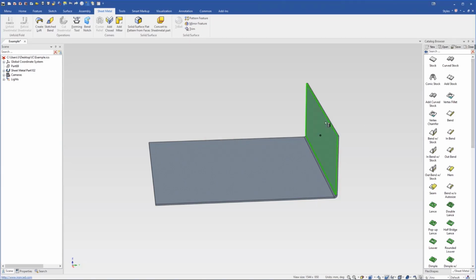And then I'll drag and drop another outbend here, and it's worth noting you don't have to drop on the exact edge. You can drop anywhere here and it'll snap there, and you press this arrow if you'd like to flip it or change the angle by 180 degrees.